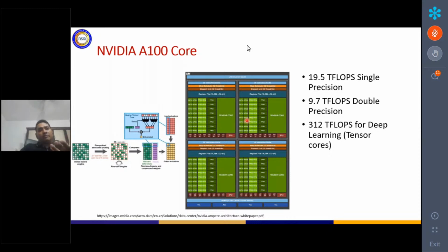Of course, that will be manifold for your 2D matrix multiplication, but you get the idea, right? Basically, where one operand is zero, you just don't do the multiplication. So in terms of energy efficiency and throughput, you can increase it manifold. That is why sparsity in matrix multiplication is introduced in these tensor cores available in the Ampere series.